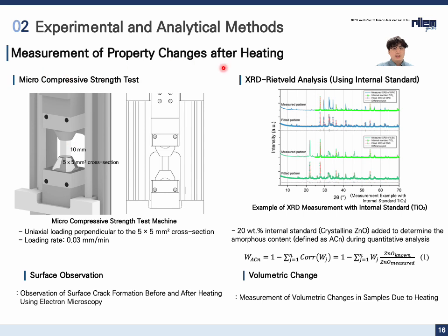For the measurement of property changes after heating, the micro compressive strength test was performed on the specimens, and XRD Rietveld analysis was carried out with the internal standard method before and after thermal exposure. And surface crack formation was observed before and after heating using electron microscopy. Volumetric changes were measured to assess thermal expansion or shrinkage behavior.